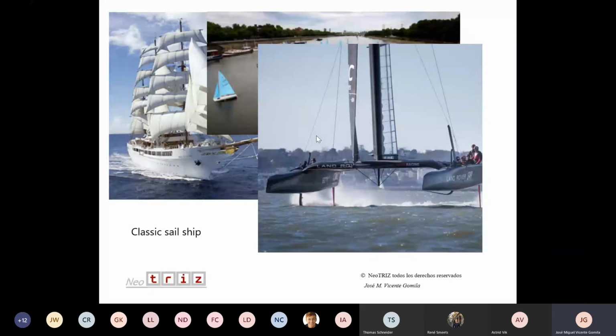I mean, the wind can be 20 kilometers per hour, and they can go 50 kilometers per hour, because again, the effect was not direct pressure from the wind, but again, the effect of Bernoulli. The Bernoulli effect, like in the wind turbines that we saw, helps them orient this and produce a large force to move the ship faster than the wind.